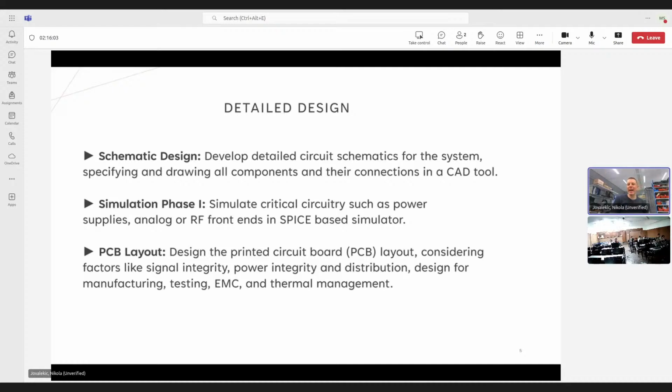So design for manufacturing. We are referring to something very, very particular here. First of all, our designs will be manufactured. So someone can think, okay, what does it mean design for manufacturing when we are anyway going to manufacture it? We are designing to be manufactured. But what is generally considered in the industry when you say design for manufacturing is the following. When you, for example, need to produce 10,000 pieces of some hardware assembly, they call it PCB assembly, PCBA, you will also face some problems with yield, or with percentage of properly assembled components.